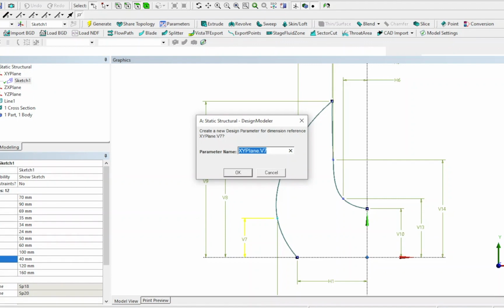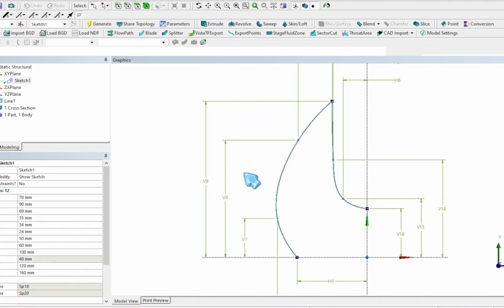By default, a small p will be activated in that box. That small p indicates that this is a parameter that you are going to optimize. You can rename this parameter as y2 to indicate that this is the y direction of point 2 of the flexible gripper. Then you repeat the same process for point 3 and also for point 6.